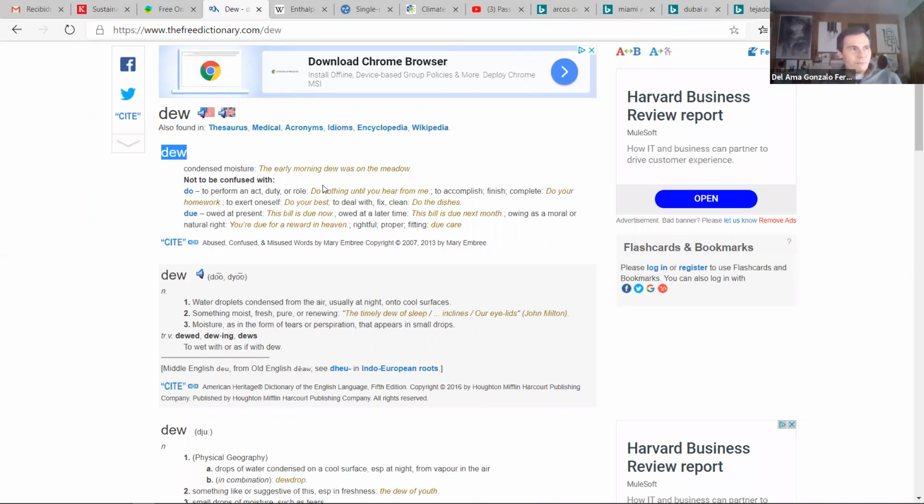Most of the thermal insulation materials, if they get wet, will lose their thermal insulating properties. So that's an issue. Wood doesn't work well with water at all. In other materials, with metals, we can have problems with corrosion if they are exposed to water, and even bricks or concrete or stones can have issues if they are exposed to water. Okay, so nothing works well with water.